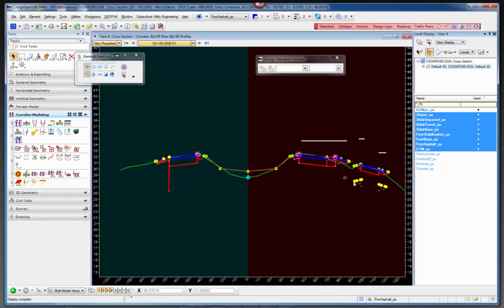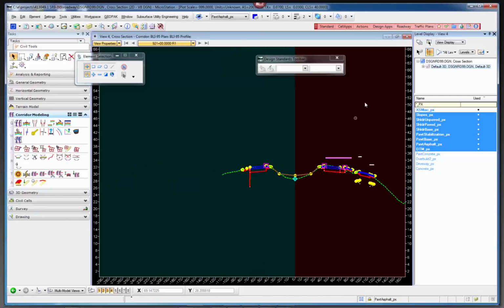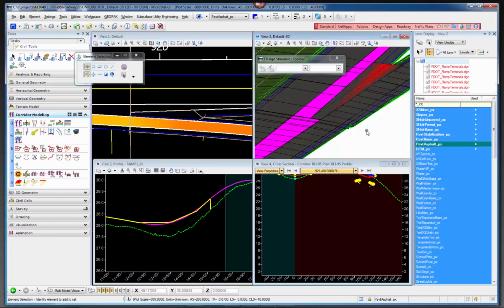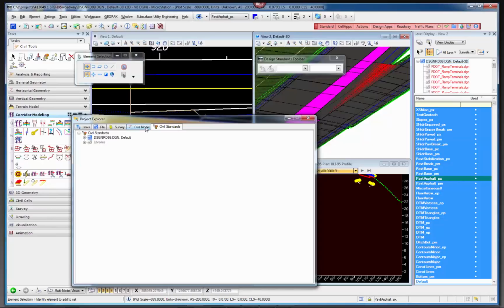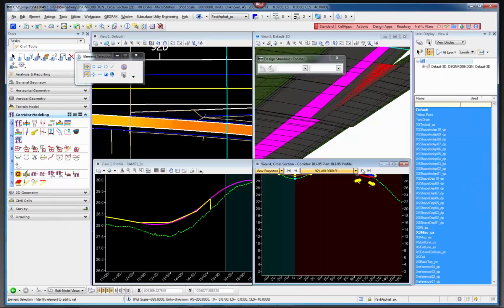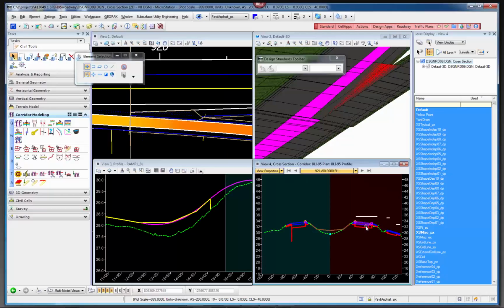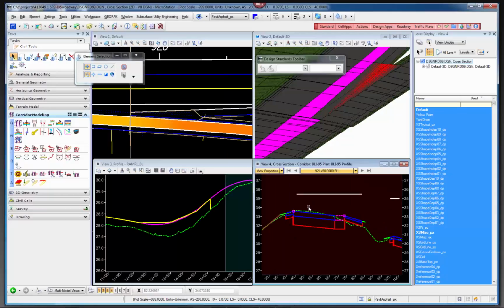As far as these yellow balls, those are in your model. It's the 3D line strings. So what I do to turn those off is I go to the F11 key and I go to the civil standards, and once this is turned active view, you can go to the features and turn them all off at once. That will turn them off there, and then the next time you move your cross sections, those yellow balls won't be turned on. Those are used for when we go to do the cross-section labeling with a new labeling tool. It needs to have those little point cells.